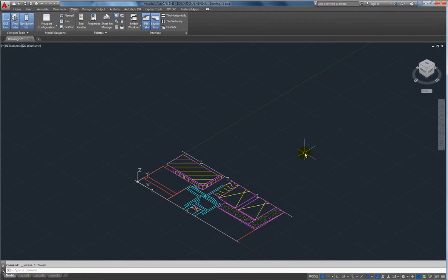So a surface is basically producing some type of extrusion that's based off of maybe initially a line, right? A profile. We typically call those profiles, right? So if we think about how even steel is made, we hear the word extruded, right? That's an extruded shape. That means that they take hot material. They have some type of template, and then, who plays with Play-Doh, right? And you squeeze it through the profile, right? And it gets extruded through that shape.